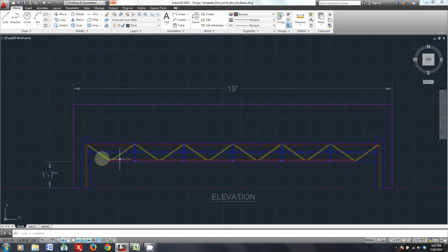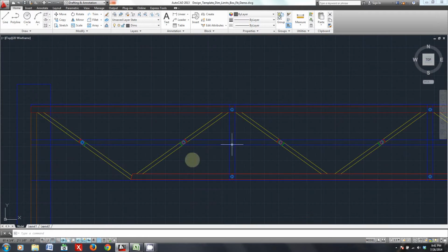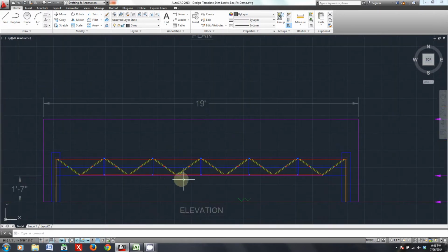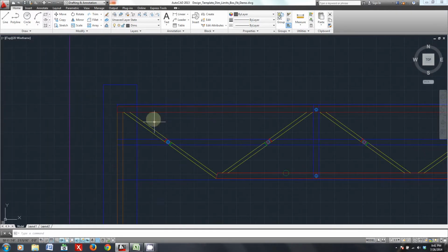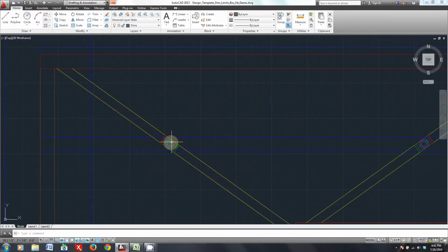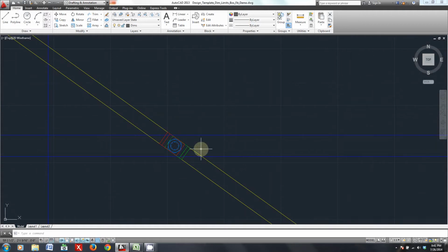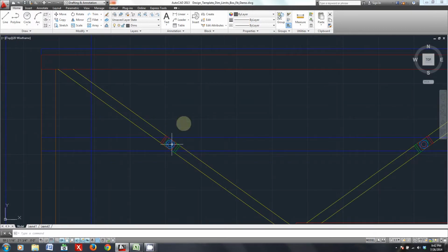So for now, I've neglected looking at the vehicle passageway rules from 2014. I'm just taking a look at a typical stacked bridge, and hopefully you recall the definition of a stacked bridge from a couple lessons ago. Here I have a top chord that goes across and a bottom chord that goes across as well, all connected together with bolts, and then we have webbings that go through like this. You can see the webbings are connected, and I'm borrowing that connection that we designed from the previous lesson. I'm using that information, my guess at what our connections will be, to inform how we go about optimizing the dimensions of the bridge.